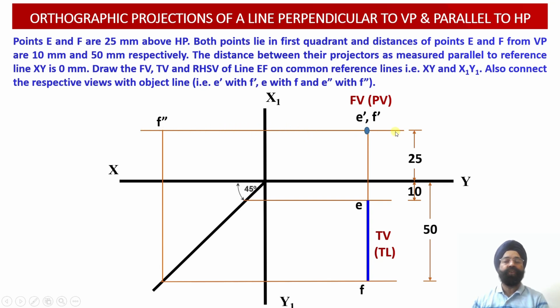So wherever these two projector lines, that is the horizontal projector line emerging from point F dash in the front view and the vertical projector line corresponding to point F of the top view, join, we obtain the location of the point F in the right hand side view projections onto the profile plane. So point F double dash has been obtained over here.